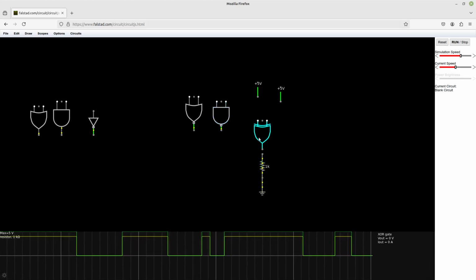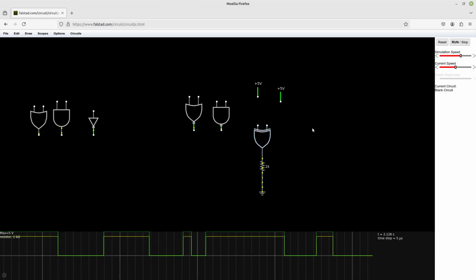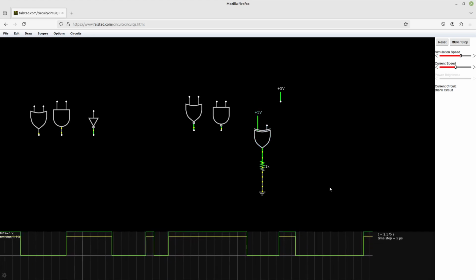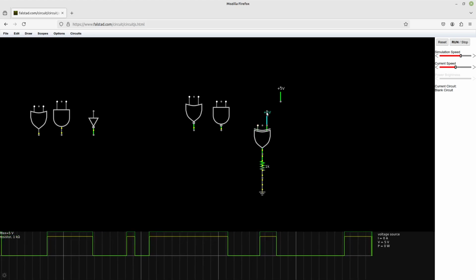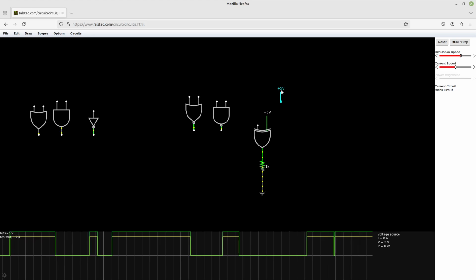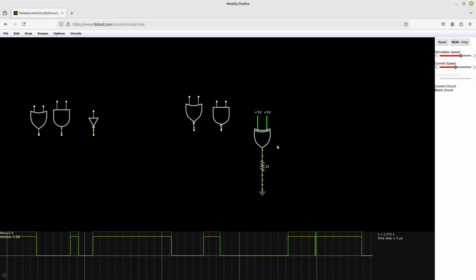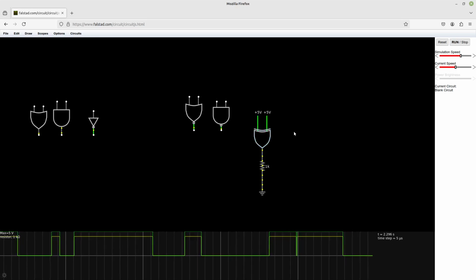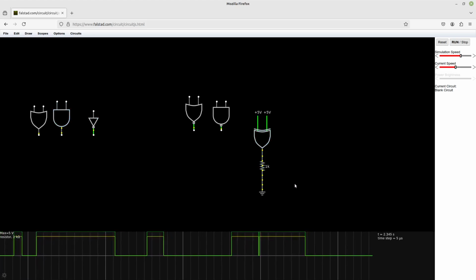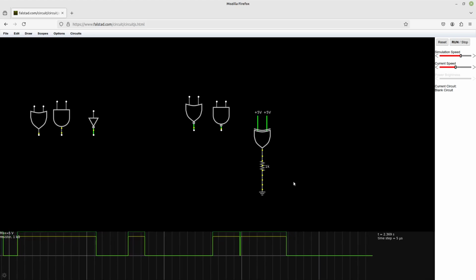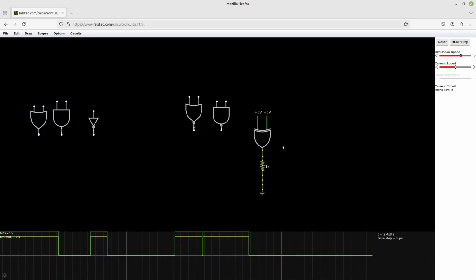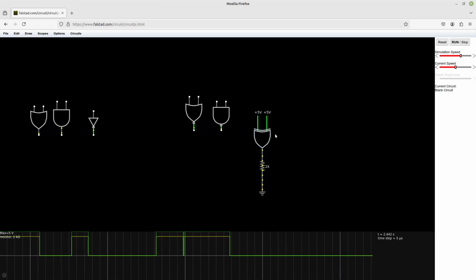This will be the last gate we'll look at today. And you may have worked with this with bitwise functions. So just like an OR gate, if this one's turned on, you have power. If this one has power on this pin, again, power comes out. Unlike an OR gate, it does not have power if both pins have voltage on them. And obviously this is useful because it is exclusively an OR gate, not an OR and an AND, which is a normal one, basically. One pin or the other, not both.